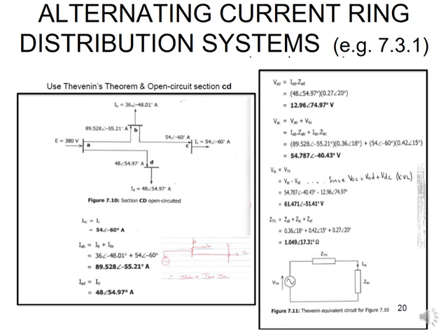And they say here that your line IBC is going to be the same as line IC. Why is that? Because you can see that it's simply a straight line. The node doesn't have any other incoming or outgoing. So therefore, that's why the current coming in that node is going to be the same as the current coming out of that node.